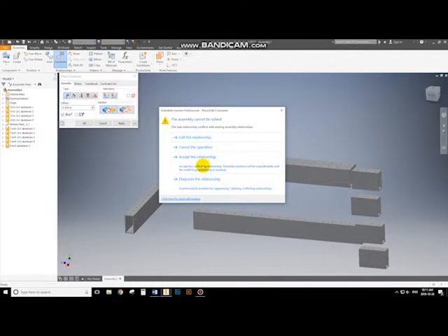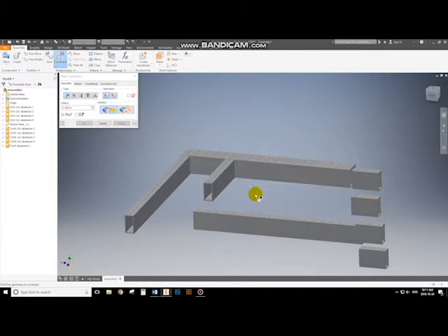What I'm about to say is vitally important, don't accept the relationship. Find out the problem and fix it using one of the other options. Selecting accept the relationship makes everything work in strange and unpredictable ways. Soon more constraints won't work either, and everything you do will end up working in frustrating and nonsensical ways. If you accept a conflicting relationship, you will die sad and alone as the conflicting relationships taunt you until your last days. Fix it, and you'll be fine.